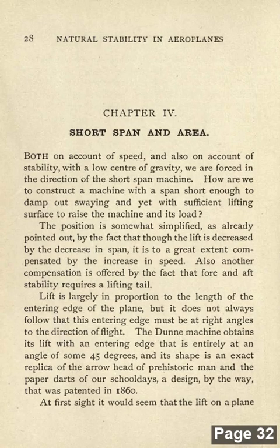Also, another compensation is offered by the fact that fore and aft stability requires a lifting tail. Lift is largely in proportion to the length of entering edge of the plane, but it does not always follow that the entering edge must be at right angles to the direction of flight. The dart machine obtains its lift with an entering edge at an angle of some 45 degrees, and it is an exact replica of the paper darts of prehistoric man and of our school days, a design, by the way, that was patented in 1860.